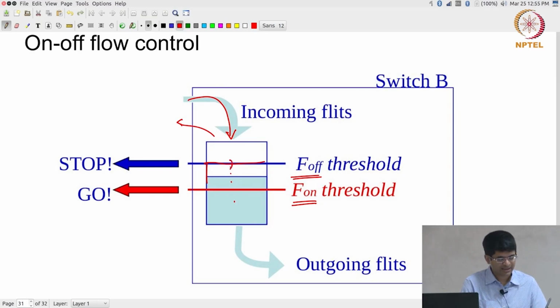The problem is, let's say that I drop below that and immediately the other unit starts sending data again. Potentially I might end up with the situation where I am just sitting over here turning it on, off, on, off, on, off. Instead we provide a slight hysteresis, let the other side clear out some data, to prevent this jumping between stop and go continuously. So when I turn off the signal, I leave it off for a short amount of time so that the buffer gets time to clear a little bit, so that when I reactivate it, it can accept more data. It's not absolutely necessary, you could just have one threshold, it will still work, but you can potentially end up with that sort of bouncing state. I clear a data, immediately one new data comes in, once again I go into stop. So I am losing cycles each time that happens.